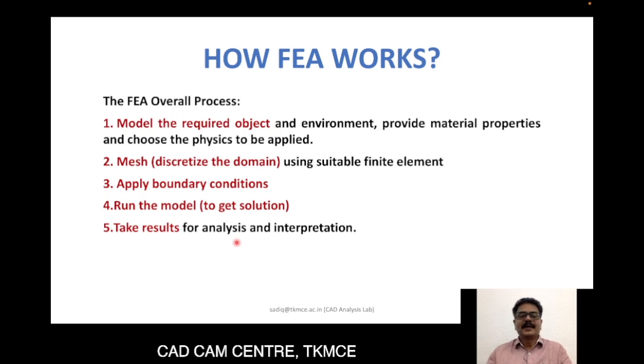For example, if I want to design a bench for my classroom where 3 students are to sit, here I have to model the bench, we have to mesh the bench, and we have to apply the conditions for that, like some supports and what kind of loads are applied. So those are the boundary conditions we are giving. Those kinds of things are to be fixed. Then we will go for the solution.